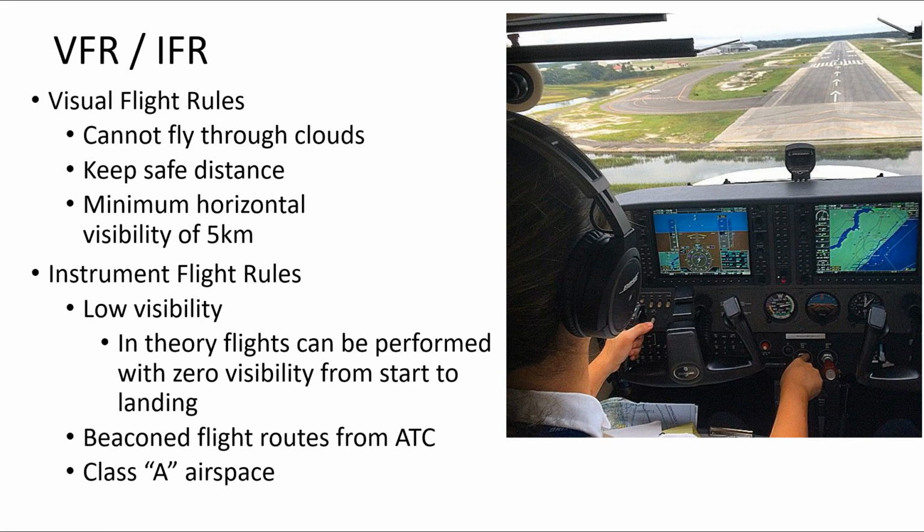And then this is our last piece before we finish today. We've got VFR and IFR, two different sets of rules. I don't know if any of you fly or are interested in pilot licensing and so forth, but VFR and IFR are two rules that they fly by. One is visual flight rules, one is instrument flight rules. VFR means you can do everything you need to do just with your own eyes, and you're manually flying everything. Small airports can only handle visual flight rules. You can't go through clouds, you can't land in fog, and so forth.